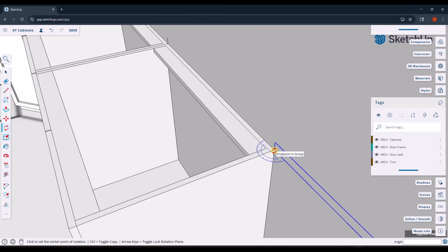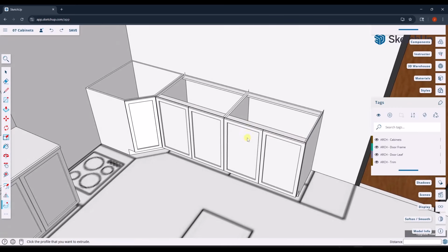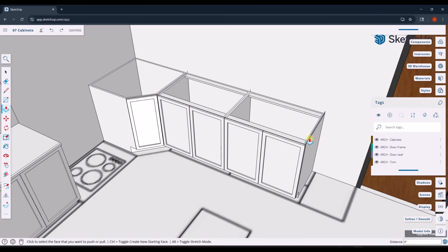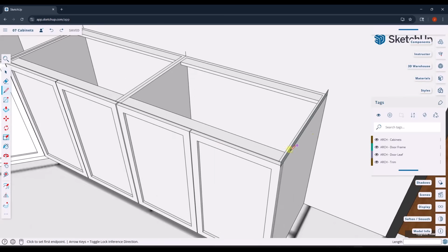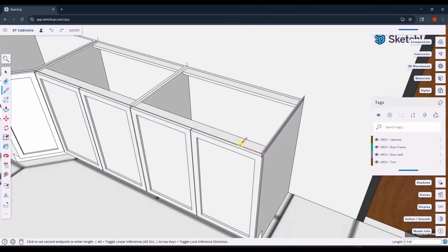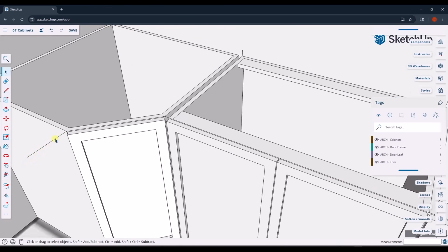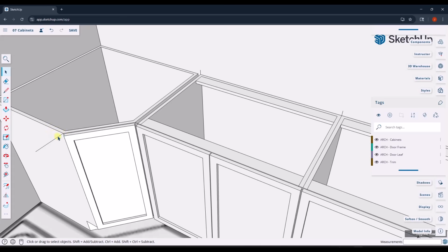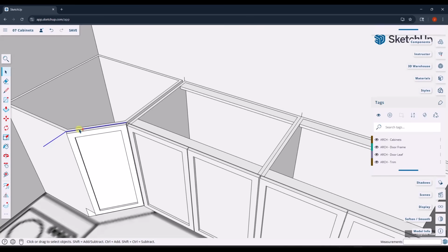And then I can use the rotate tool in order to rotate it. So in this case, instead of me trying to manually model this, because you're going to extrude this profile across, but then you need it to turn the corner here, one thing that I find extremely helpful is I can use the Follow Me tool. I'm going to draw a path here, but then I'm also going to draw a little bit of a path here so I get some overlap, because otherwise it doesn't do the final orientation on the side and it doesn't give you a very good result.